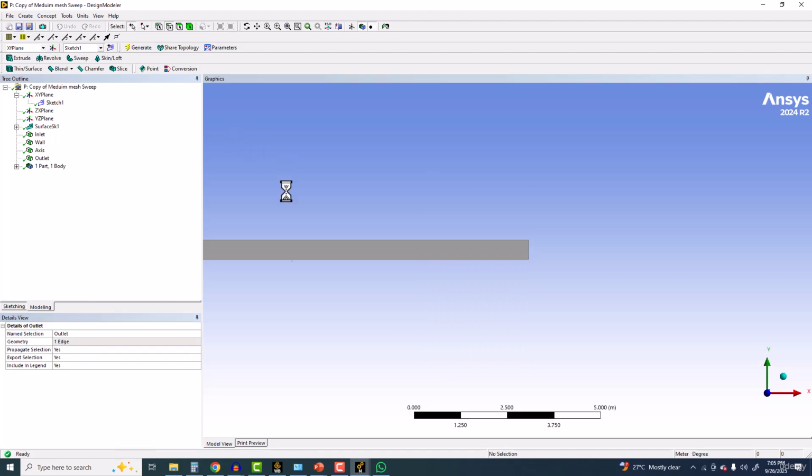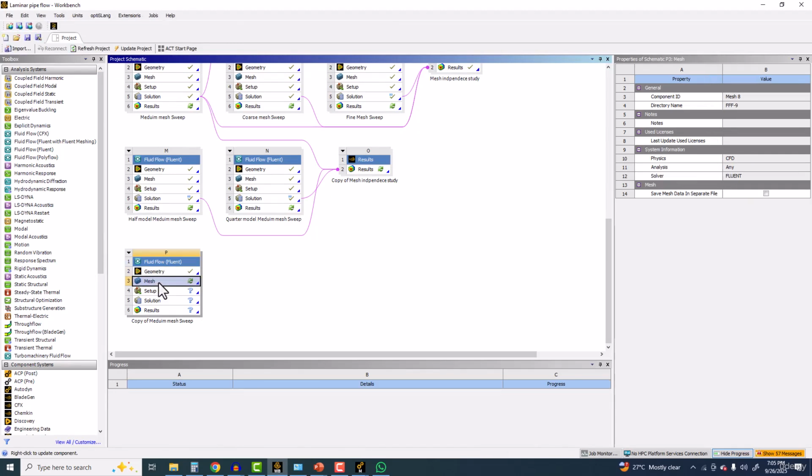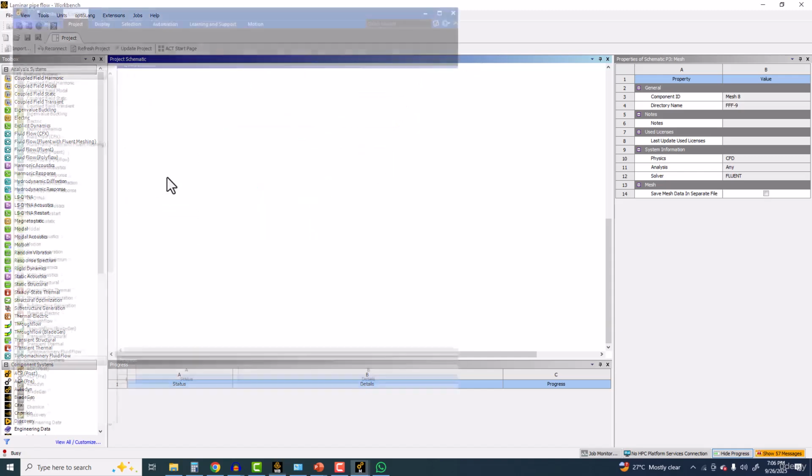Okay, that's all. Now I will double click on the meshing, and this time the mesh distribution will be exactly the same, with 50 cells across the length. But diagonally, because now this contains the inner box and the diagonal edges, we will be making the number of cells around... let me check what was there in the 3D case.